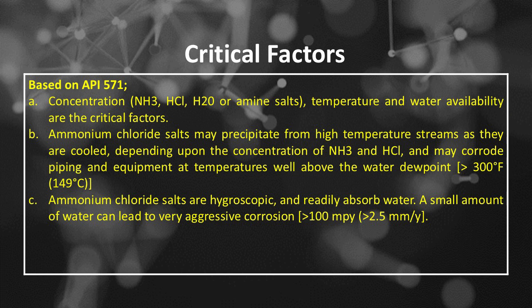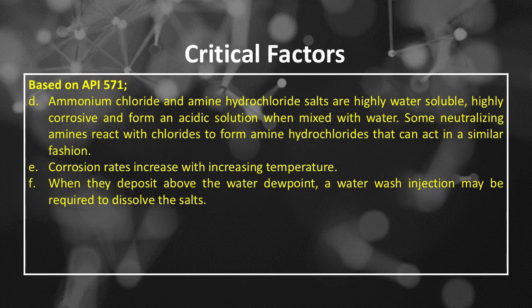Number C: ammonium chloride salts are hygroscopic and readily absorb water. A small amount of water can lead to very aggressive corrosion, greater than 100 mm per year or greater than 2.5 mm per year. Number D: ammonium chloride and amine hydrochloride salts are highly water-soluble, highly corrosive, and form an acidic solution when mixed with water. Some neutralizing amines react with chlorides to form amine hydrochlorides that can act in a similar fashion. Number E: corrosion rates increase with increasing temperature. Number F: when they deposit above the water dew point, a water wash injection may be required to dissolve the